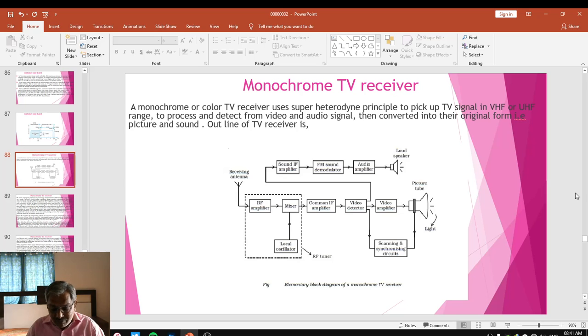That is at the end of the odd field as well as at the end of the even field, to interlace both fields with each other and also to keep the screen blank during both the retrace periods, where the returning beam doesn't contain any picture information within it. Also, these are used to synchronize the transmission and reception with each other.